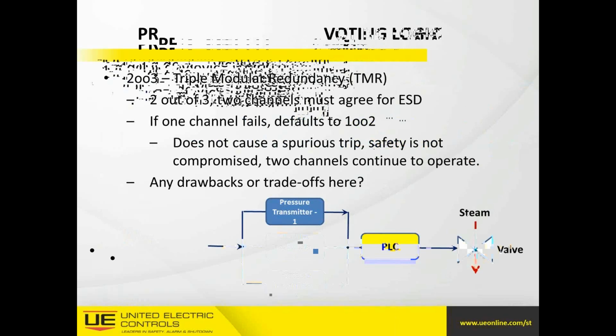So what companies are doing, a lot of corporations are looking at this proof testing average, this interval, and trying to figure out for themselves what works best to lower the risk, and then how to do these proof tests. Keep in mind, when you proof test a device, you take it out of circuit. You take that safety instrumented system out of protection. So how long will that go? How long will it last?